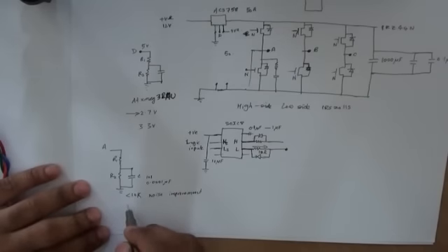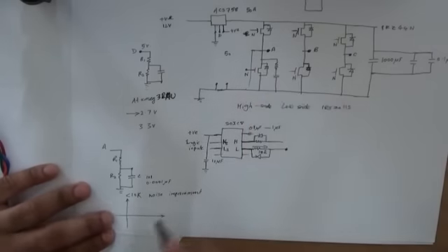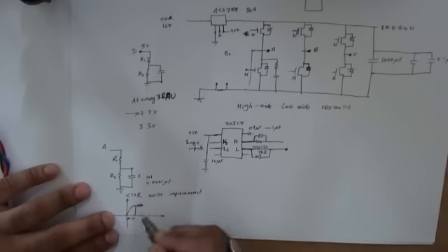So, for example, if you look at the pulse that you will see on phase A, it will be something like that. It will die down depending on your duty cycle of your PWM. So if your duty cycle is that wide, and if you had a bigger capacitor, it will be something like that, and you don't want that.